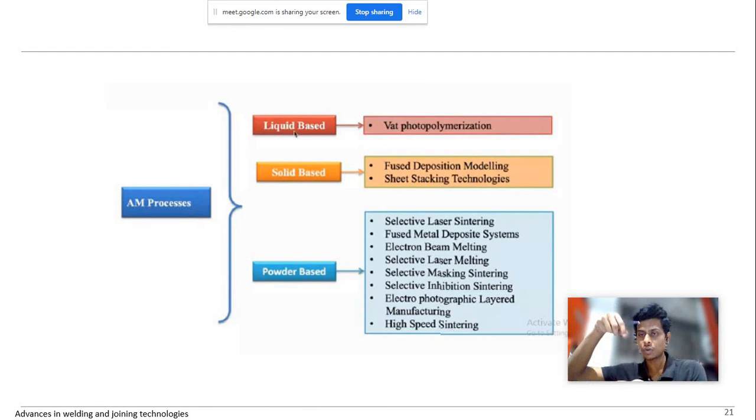help of a laser power source, as discussed in the last class, whatever the tool path is, it will travel, and because of the laser power source the material gets reacted, and basically it will get solidified, and we'll get the layer component.